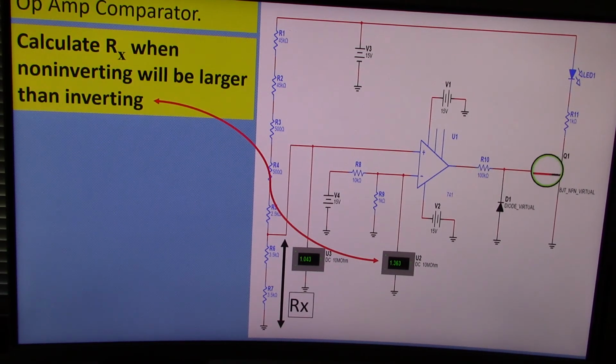You don't want to actually apply negative 15 volts to this base, and that's what this diode does. It takes that negative 15 volts and forward biases this diode to ground. So you'll have a path of current like this. That's if this number is 1.3 and this is 0.